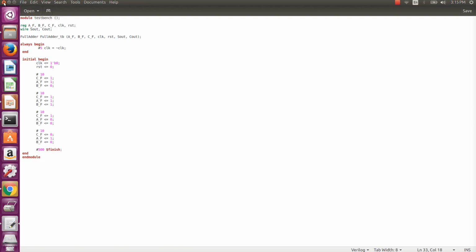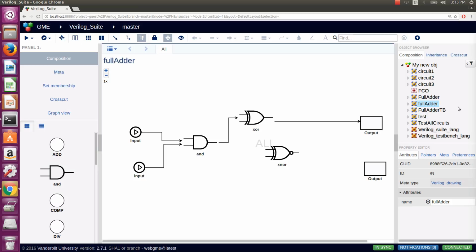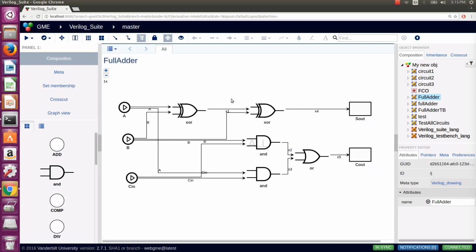So these two files, verilog.v, the Verilog file that was generated after using the tool, and the test bench is used as an input in Xilinx Vivado tool to create the waveform that you saw in the slides earlier. So this is one of the basic examples.